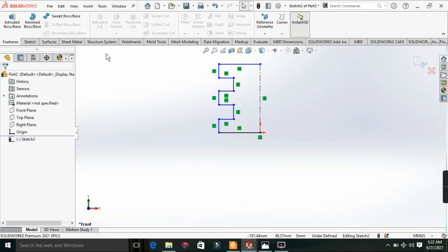If you want to do this using normal Revolve Boss, it will probably message you asking if you are sure you want to revolve this sketch, because we have open sketch and closed sketch. This drawing we are drawing here is an open sketch, because from this point to the origin it is open. The center line is just trying to show you that something is there, but it is not closed. Center line is not a real line. Are you getting it?